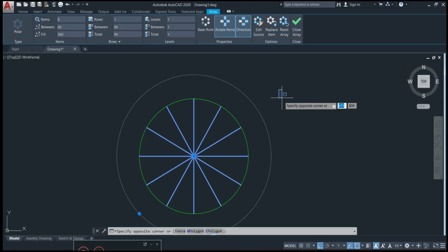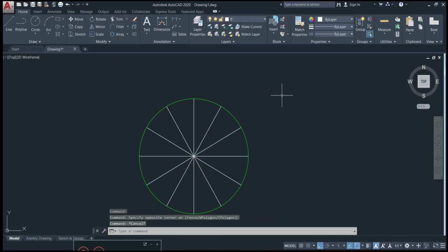Alright, so let's go. Once you have divided the circle into the number of divisions, the next step is to draw your tangent from each division point. I'll draw a tangent to the circle. These tangents will represent the directions of the string at each interval as it's being unwound.